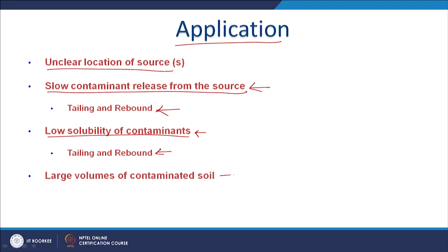And obviously if the volume of contaminated soil is way too high and it's not feasible to have either ex situ or in situ treatment of the relevant soil, let's say, what can I go for? I can have this passive technique, as in I place these PRBs at strategic locations, capture the plume, and then let the PRB do its job now, right.